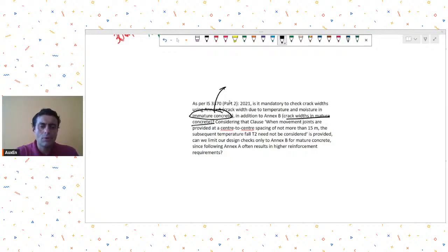And see, what you can do is, you will have cracks in the concrete because there will be shrinkage related cracks. So what we desire to have is well distributed fine cracks. Okay, so by controlling the water cement ratio in the concrete, by providing reinforcements which are at close spacings, you could have well distributed fine shrinkage cracks in immature concrete, which will not be a problem for you.